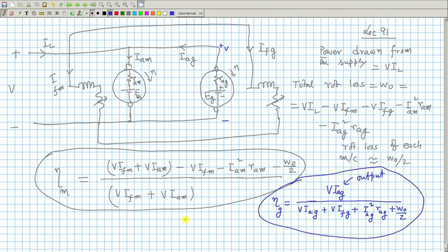So, you see, in this experiment compared with Swinburne test, here you will be able to load the machines to their rated current, but supply will never know. Supply will only supply the losses. So, current drawn from the supply is not large, a little current IL, which comprises the copper loss of these two field coils and armature copper losses and rotational loss, that is all.